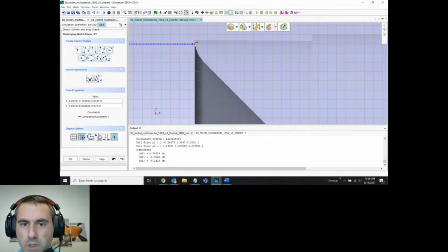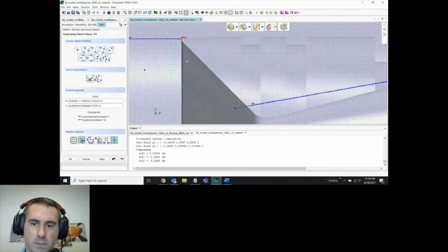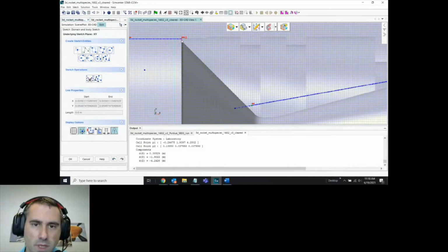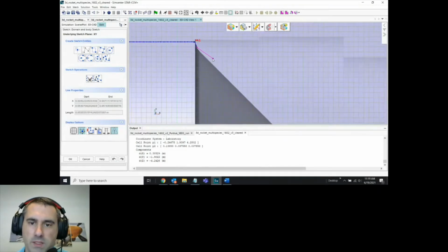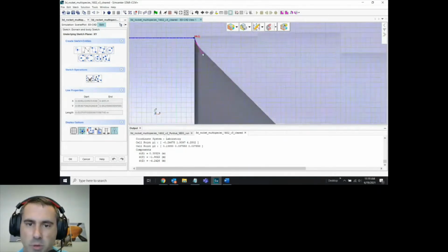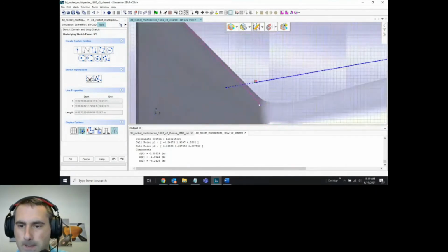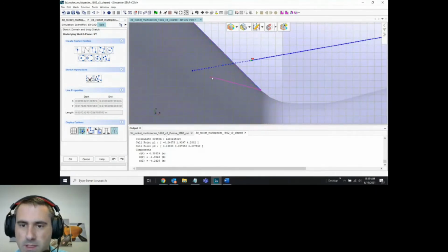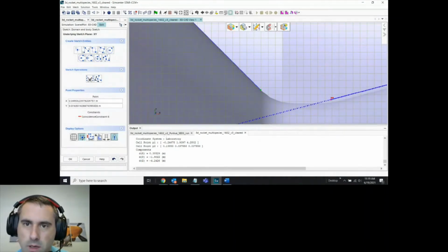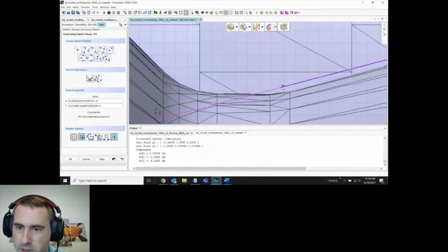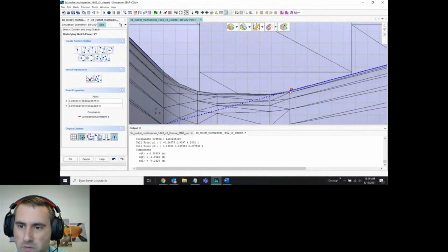So what I'll do here is I'll set a fixation constraint. And you don't want to do this for too much of the geometry, because, well, you'll see here in a moment that I'll have to rename a few of the surfaces. So that's good like that. Okay, and I'm going to turn on this tessellation. Okay, I can see it kind of stops. Whoops. Go back to the last view. Move this to be down here.